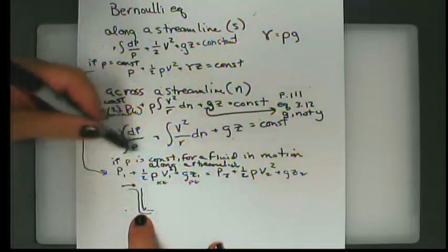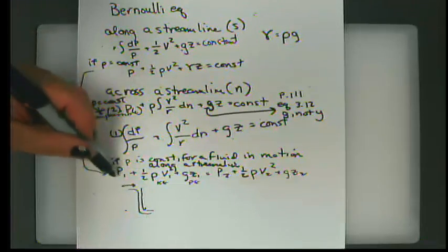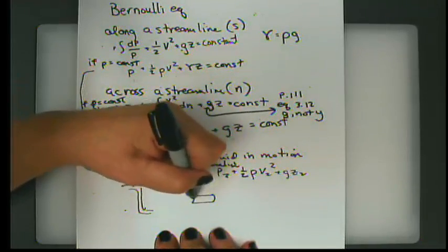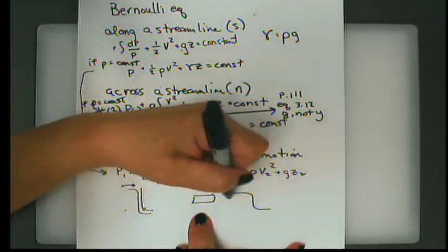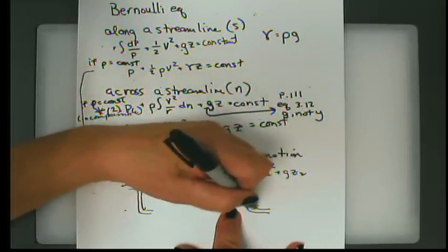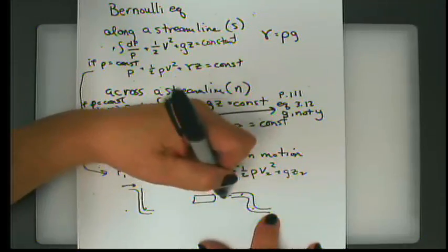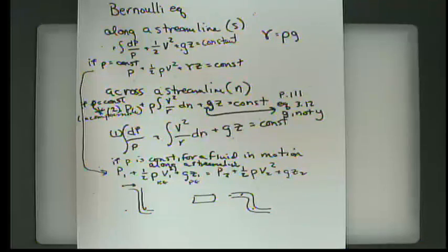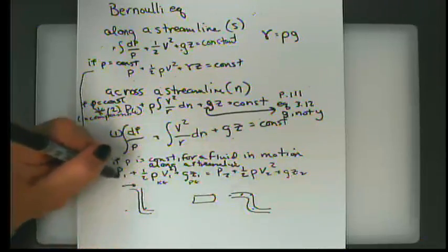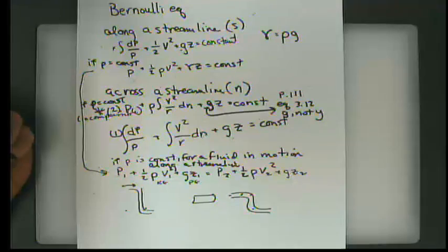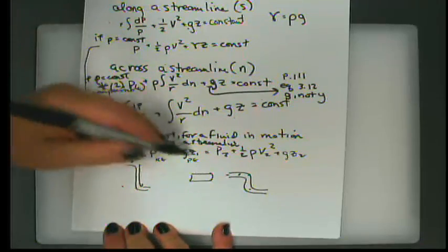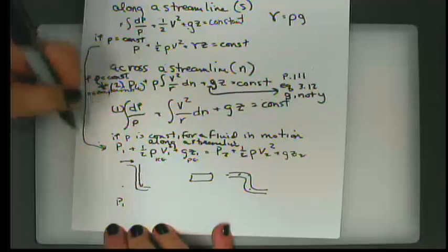But when we have a fluid moving, especially in an open system, the pressure doesn't change. But when we have a conduit, like if you have a pipe like this, for example, there's going to be pressure differentials possible from here to here. Where it's open to the outside, we know from our manometry studies that that won't be different at those points. But if you can change the pressure, then you can trade off some pressure energy for potential energy or kinetic energy as well.